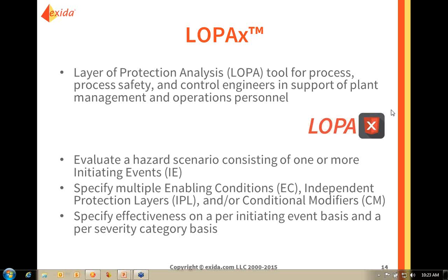I would tend to consider them as one layer of protection, one out of two, with a common cause factor. That's a little bit more conservative, and of course you need to make sure that each relief valve is sized large enough so that it can actually prevent the hazard from occurring. But I would tend to go with a one out of two approach and a common cause, which is going to help you significantly, but it's a bit more conservative.